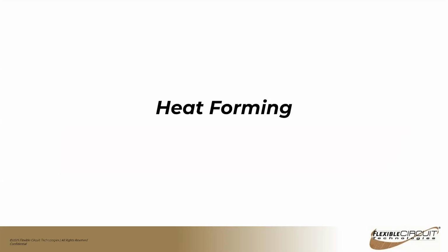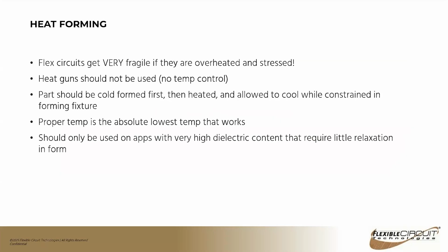So heat forming, flex circuits do get very fragile if they're overheated and stressed. Heat guns should not be used. There's no temp control. If someone was using a heat gun, that could vary from operator to operator, how far they're holding the heat gun. So you should never use a heat gun when forming a circuit. Parts should be cold formed first, then heated and allowed to cool, constraining the fixture. And the proper temp is the absolute lowest temp that would work.